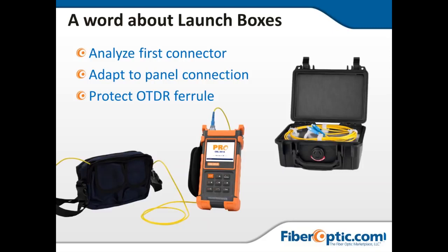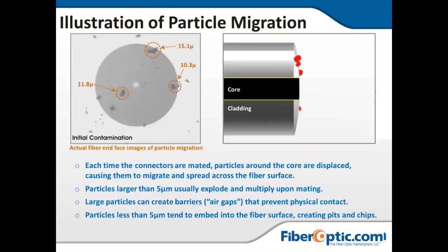Otherwise, it's really hard to troubleshoot these things when you don't have a launch box, because if there's dirt and debris on that first connector, we can't measure it. You start to assume it's equipment failure. You start to make all these assumptions that maybe aren't true.